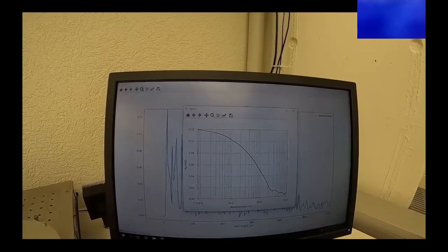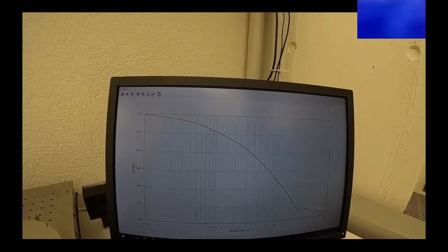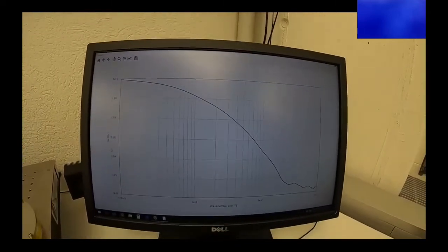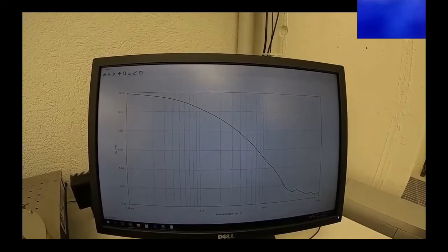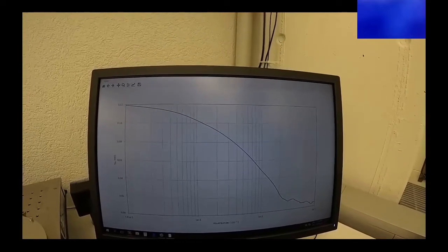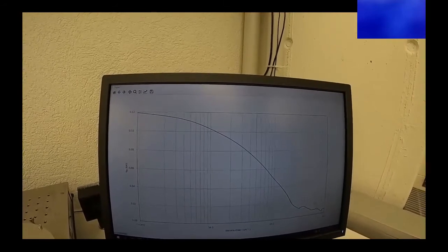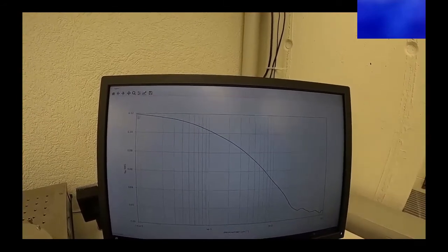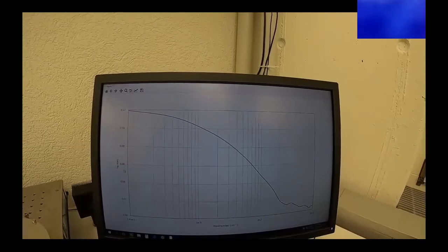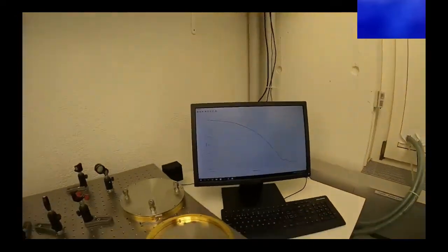And this is exactly what we do in this last plot. So here on the y-axis we have the root mean square of the signal that we had just on the plot before. So this would be in per mil. And on the x-axis, we have the wave number resolution. So again, as we go down with the wave number resolution, we have higher optical fringes or higher noise. And for every cell that we ship, we measure this plot and then make sure that we are always below the value that we specify, which is 0.2 per mil. So that is with optical fringes.